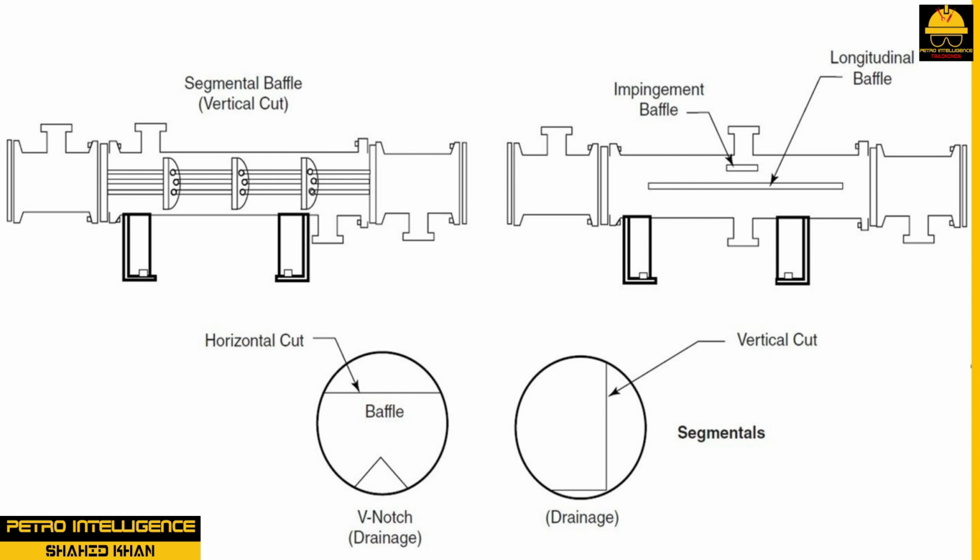Single-pass exchangers do not need a baffle in the inlet or return head. Multi-pass exchangers requiring 2 passes will have a single baffle in the inlet channel head. A variety of baffle arrangements are available. Cost goes up with each pass. Additional passes are often needed to provide adequate fluid velocities to prevent fouling, internal buildup of material, and to control heat transfer. Segmental baffles, as shown in the picture, are often used in horizontal shell and tube heat exchangers.